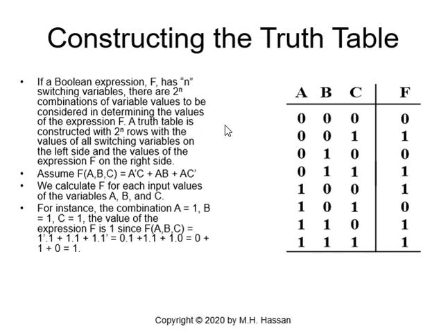Now we'll take an example to understand this. Let's start with the truth table. I have 3 input variables a, b, and c. So I will fill up the truth table. I will put a line to signify the output f. Now c will be the least significant bit, so we alternate 0, 1, 0, 1, 0, 1, 0, 1. We have 8 rows. Why? Because 2 to the power 3 equals 8. Then we fill up b, the next bit, which is 0, 0, 1, 1, 0, 0, 1, 1. And the most significant bit will be 4 zeros and 4 ones: 0, 0, 0, 0, 1, 1, 1, 1.